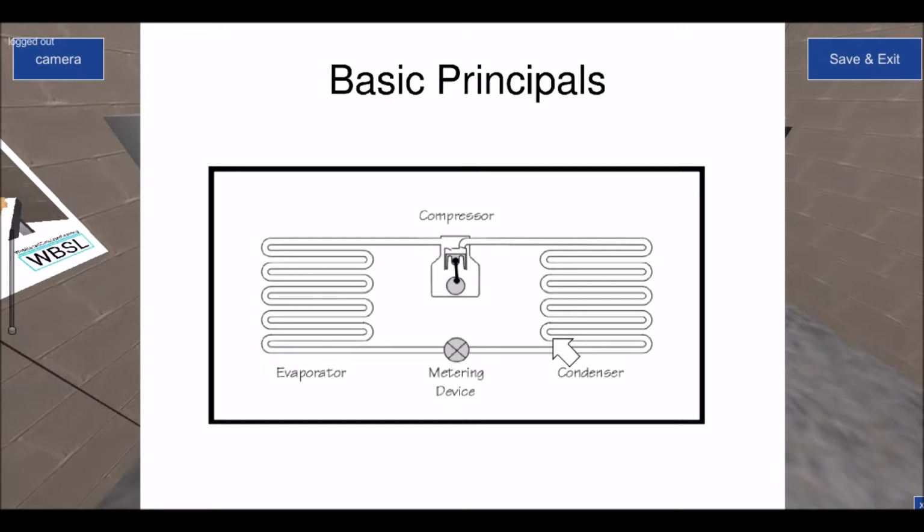When you have 100% liquid and that liquid is still being exposed, in this case if it's an air-cooled condenser, to the air, that air is actually a cooler temperature than the actual refrigerant that's circulating inside the heat exchanger. Therefore, that 100% liquid refrigerant now becomes cooled to a temperature lower than that of its saturation temperature. In other words, it becomes a subcooled liquid. So the last pass in your condenser is the subcooling zone.